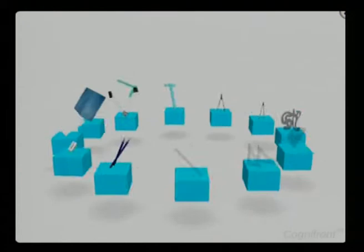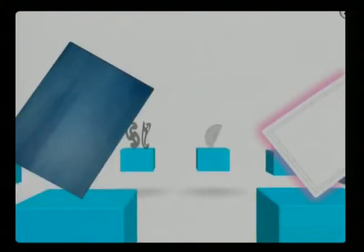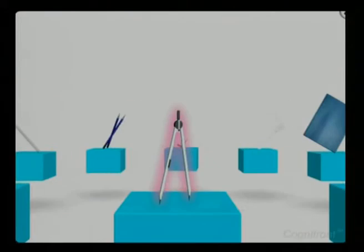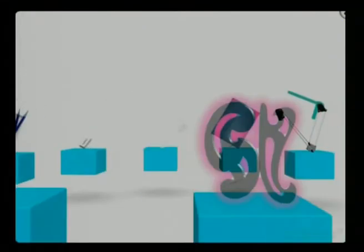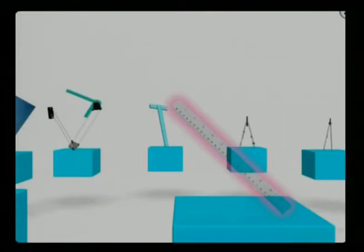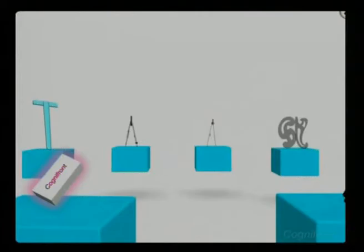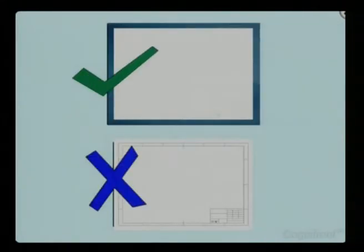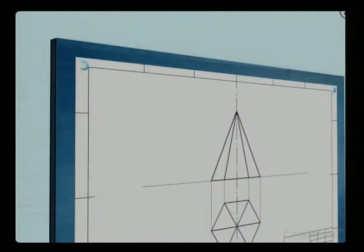So let's take a look at important tools used in engineering drawing: drawing paper, drawing board, drafter, T-square, compass, divider, French curves, protractor, set squares, scales, pencils, erasers. Before you start drawing, always make sure that the size of the drawing paper is less than the size of the drawing board. Also make sure that the paper is fixed properly with drawing pins and is smooth without any wrinkles or folding marks.